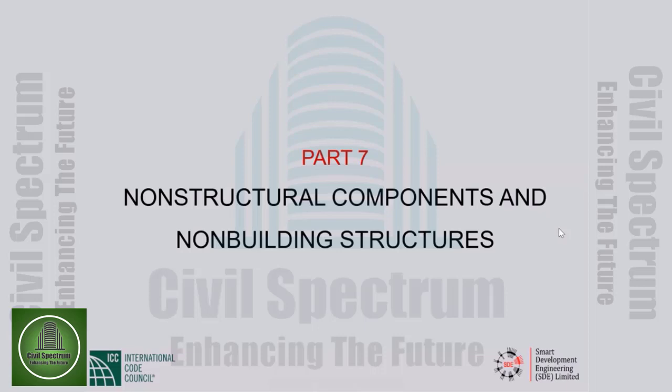Which load case or combination shall be considered for checking torsional irregularity? Torsional irregularity does not have anything to do with load combination, is it? Torsional irregularity, I gave you, when you calculate the deflections. Again, I see. Okay. My answer will be the same. We are talking about the lateral deflections. And when we are talking about torsional irregularity, we are really talking seismic.